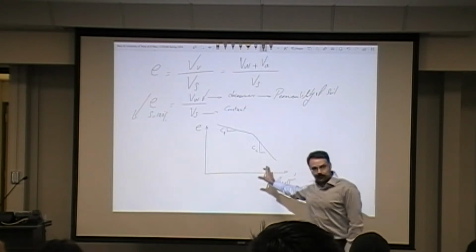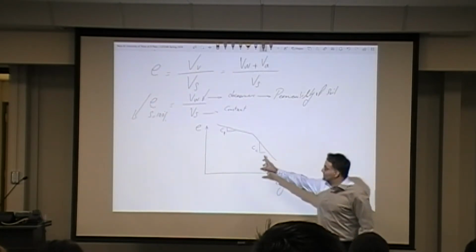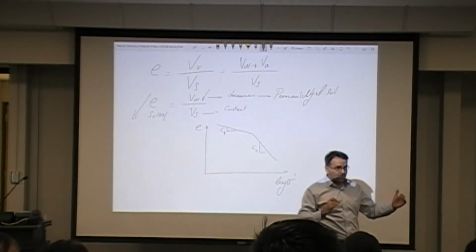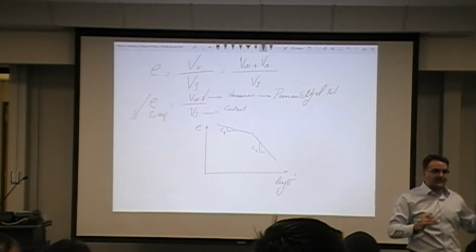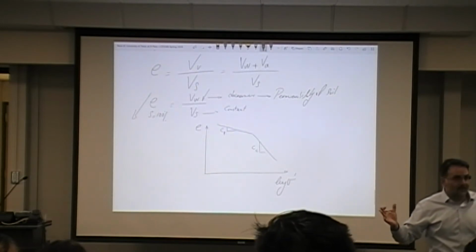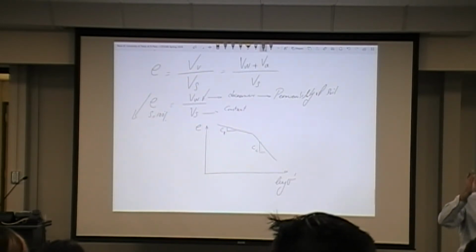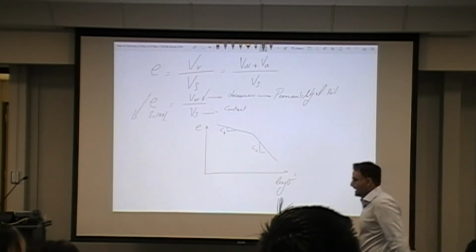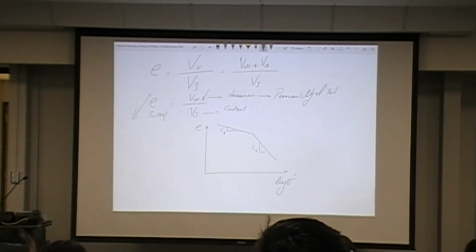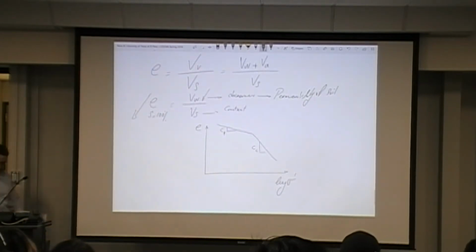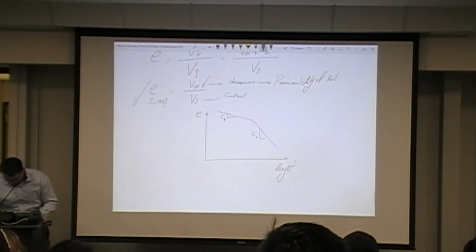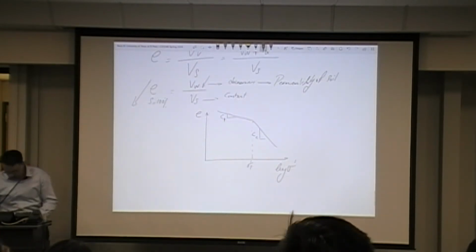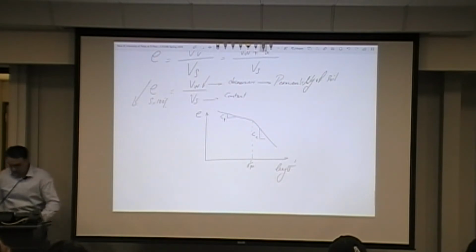What are the things that we are interested in here? We are interested in two slopes, right? Because the behavior of the material is going to be very different on the left-hand side and the right-hand side of that plot. And also we want to figure out when that change in the structure of the material will take place, right? So for that, I need to also be able to figure out what that sigma prime naught is. That would be sigma prime sub p.